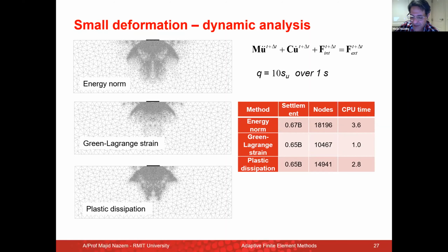Yeah, that's one of the complexities. You and I have seen many applications of h-adaptivity and remeshing techniques in the literature. One area that I think makes this more complicated is contact mechanics problems, especially when you have an interface or changing boundary conditions between an object, a penetrometer or a structure, and the soil. In my experience, when you have contact mechanics involved in your problem, it becomes even more complicated.